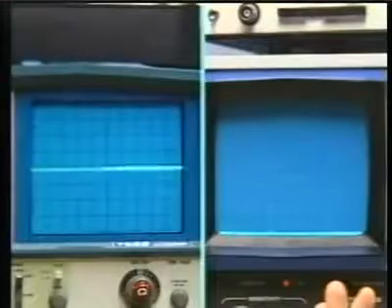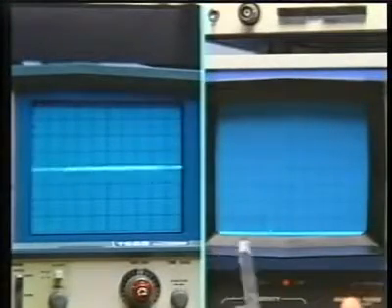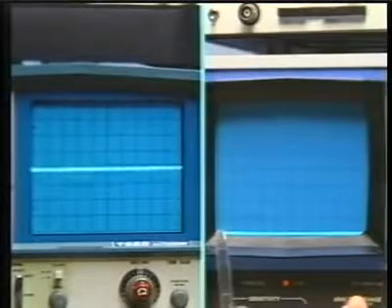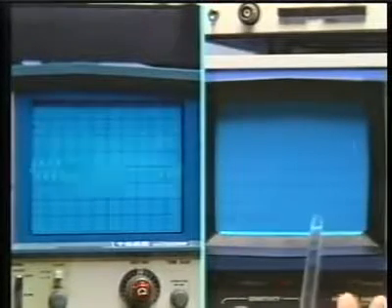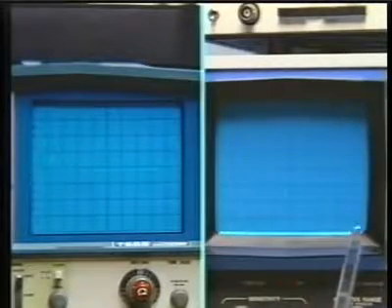What we'll do is look at the spectrum of that and then compare that spectrum when we play the tape at half speed and also play it at twice speed. So let's play the tape, and what we have is the glockenspiel right now displayed on a frequency scale from 0 to 5 kilohertz. Let's just change that to 0 to 10 kilohertz.